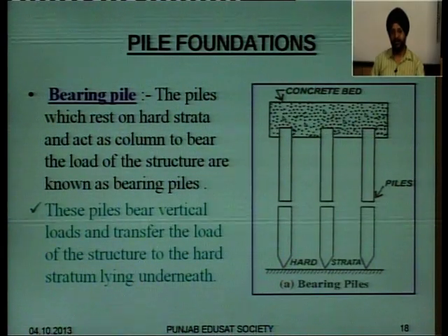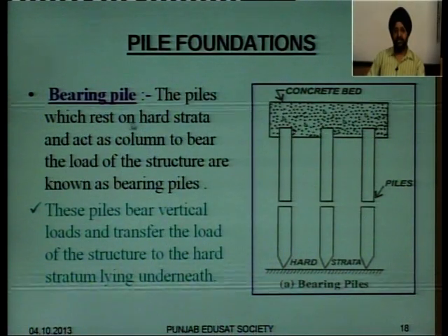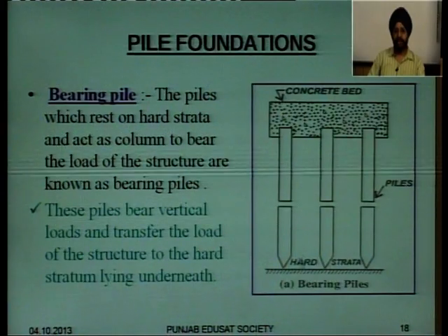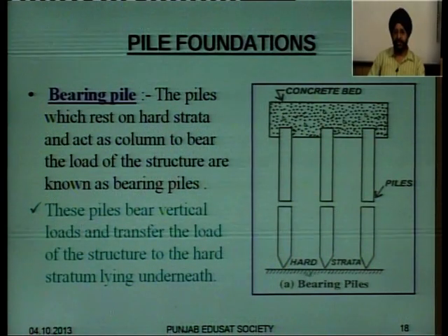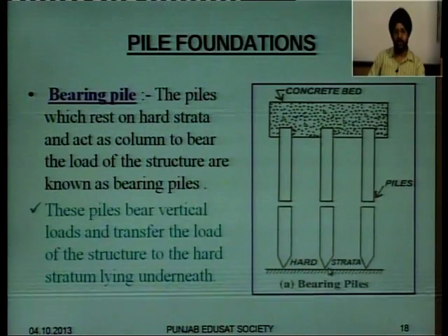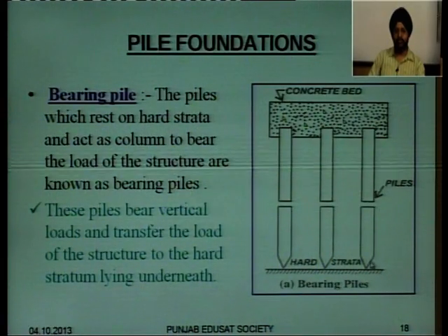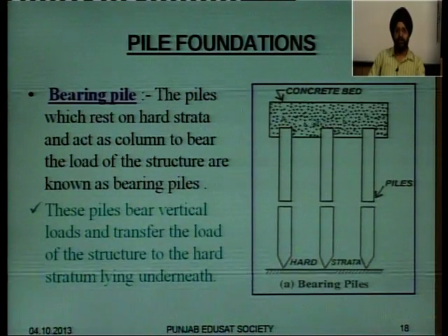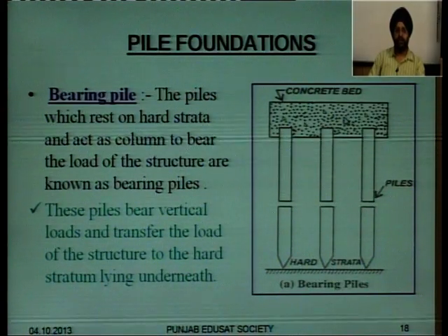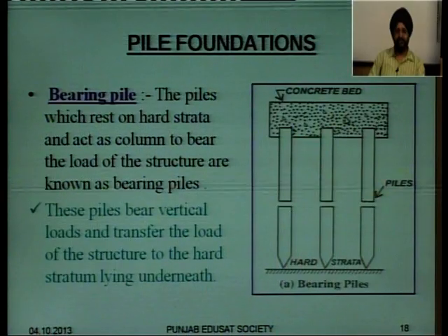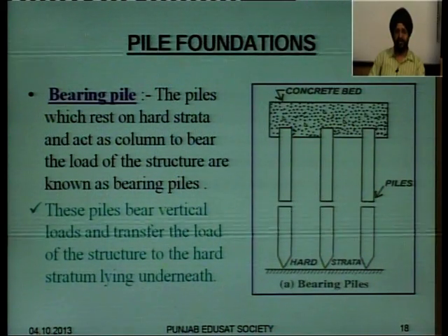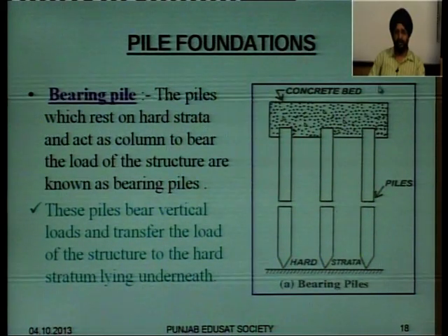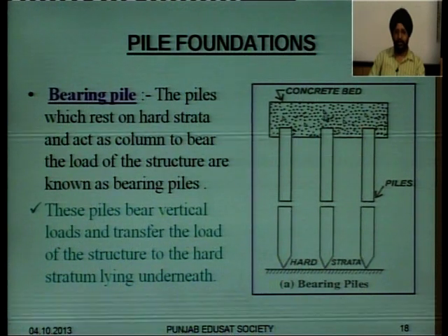Firstly, the bearing piles. What are these? The piles which rest on the hard strata, it may be rock, and act as a column to bear the load of the structure are called bearing piles. These piles are actually bearing the whole of the load coming on them.